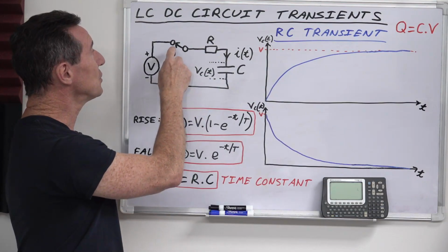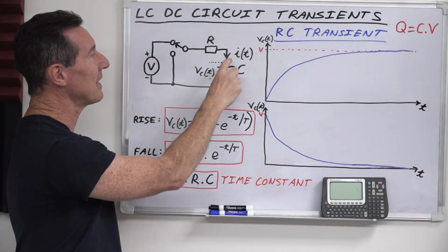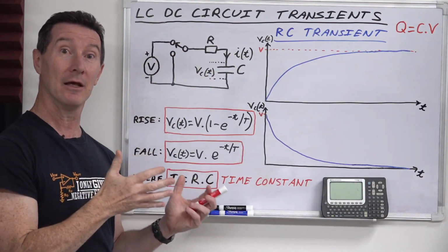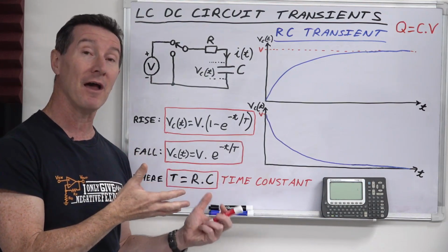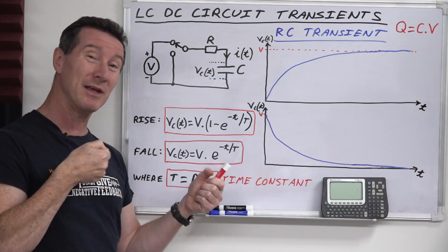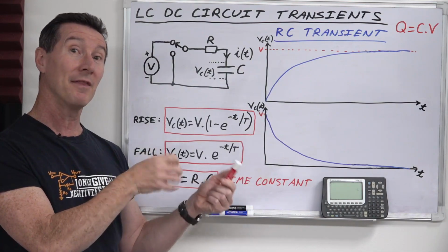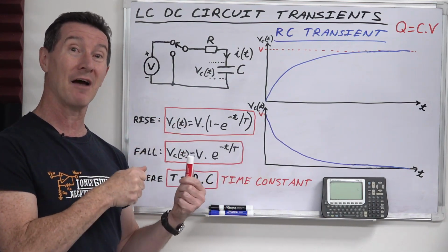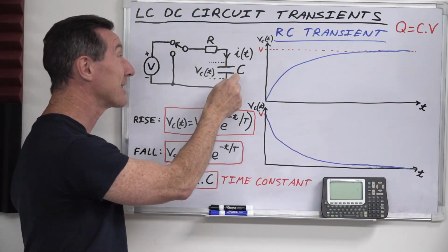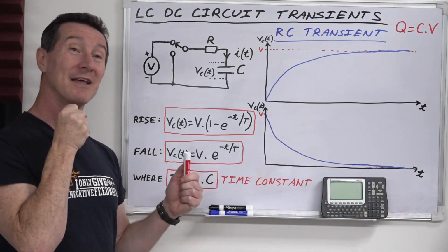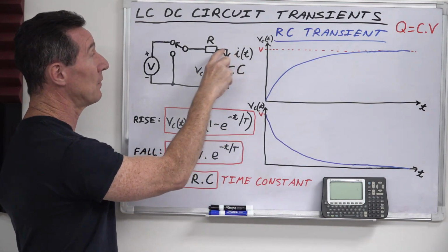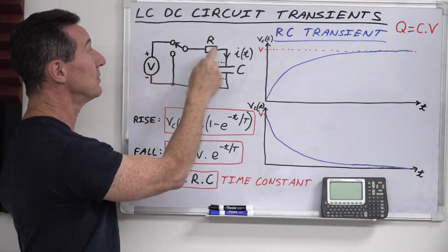So that's why as soon as you apply the voltage over here to a discharged capacitor, this capacitor, it's a short circuit. And this is why you can actually get lots of issues with large values of capacitances, particularly in power supplies. Have you ever wondered why, when you often plug a mains cable into a big thumping power supply that has big DC capacitors there after the rectifier, you might get a spark or something like that? That's because there's a lot of current flowing, because the capacitors are a short circuit. So you're going to get this surge of current flowing, and the current, of course, because this capacitor is a short circuit, will be just V divided by R.